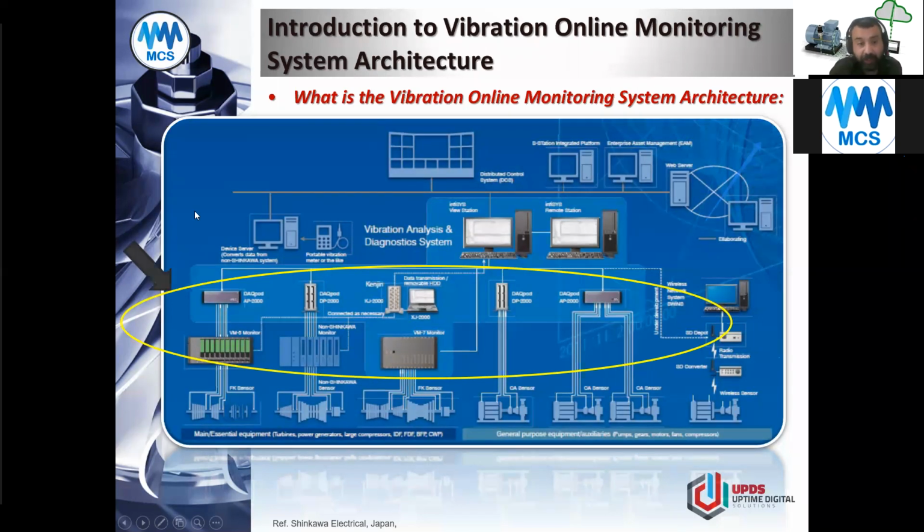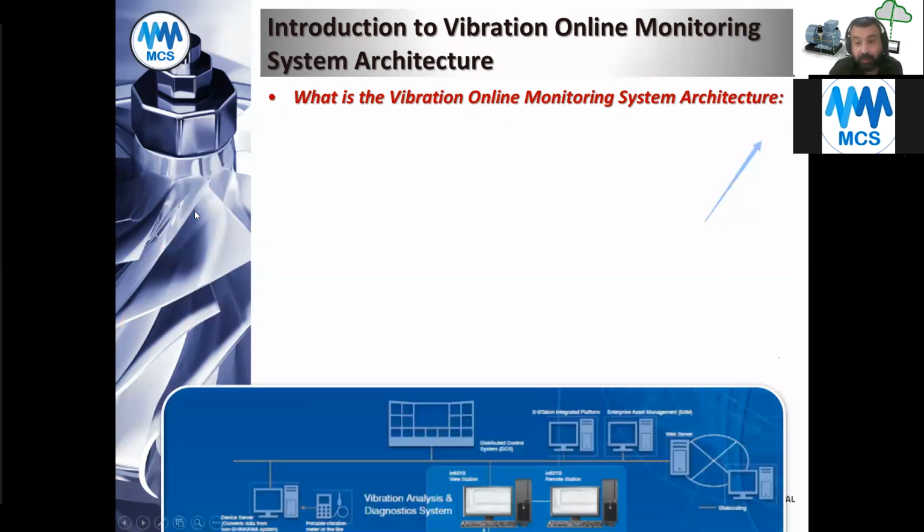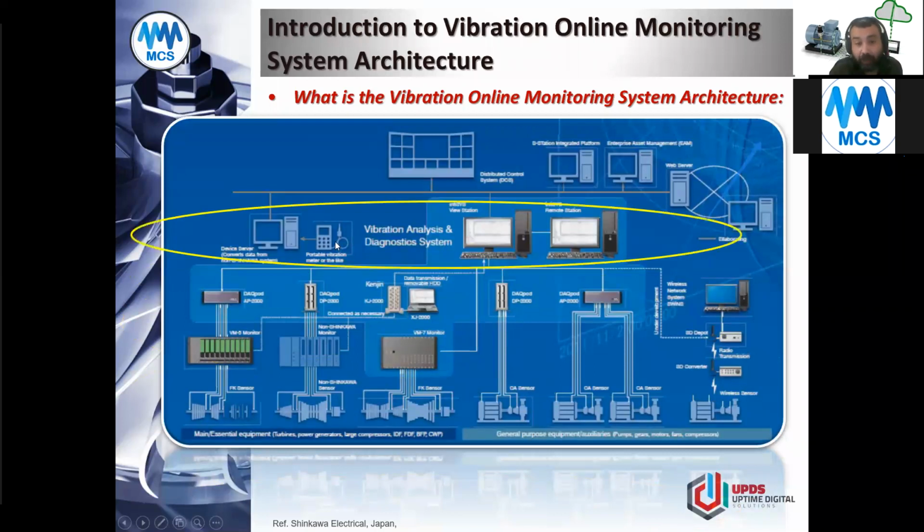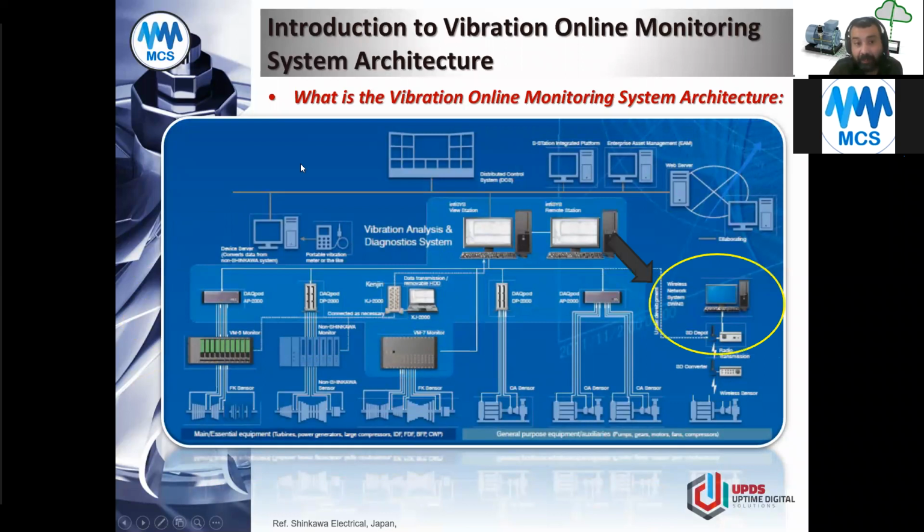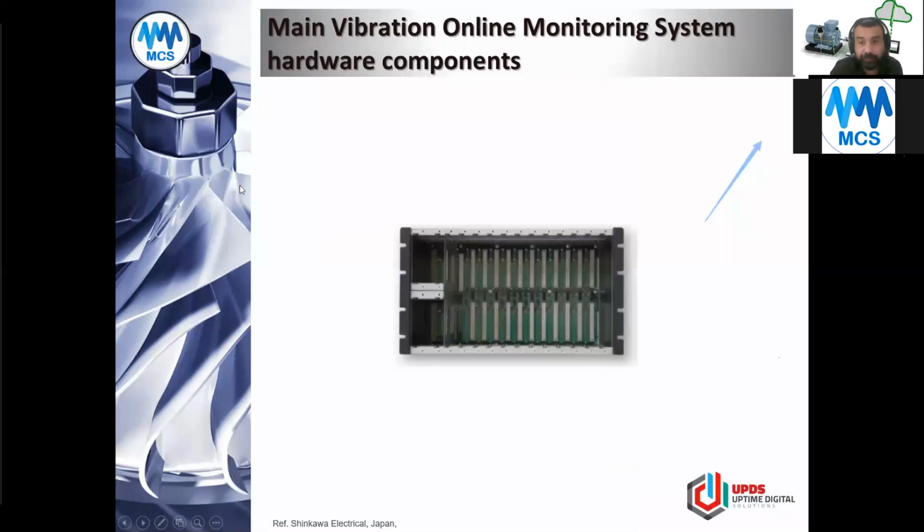We don't have time to discuss it all. Then you go to what we call the vibration analysis diagnostic system level. One thing here is very important for the future, you're going to see it a lot: the OPC, where you need to combine the vibration values with other sensors I told you about, so these sensors can speak together to build the logic. That's why I put it on the side of my presentation.